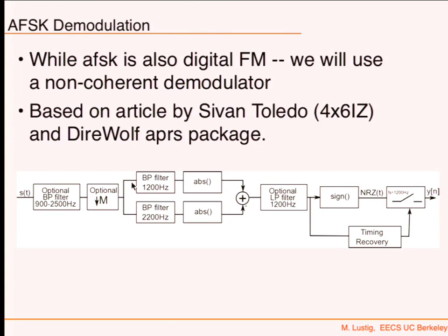The thing is, when somebody sends you packets, you don't know when it starts. You're just collecting data. And how do you know how to lock into the beginning of a sample, of a packet? You really need to be able to lock. And so we added this component of timing recovery using a simple, what's called a phase lock loop. Basically, it finds the right timings.